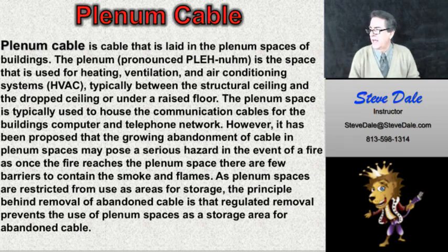And I don't have a good representation of that here, I don't think, to show you. But in any case, what you have to remember, though, in those spaces, you're required to put plenum cable, or the cable has to be in conduit. Now, plenum cable is more expensive. However, it's been tested, with a certain kind of insulation material and so forth, and basically it's going to produce less smoke, less toxic smoke, and it's going to burn slower, okay?